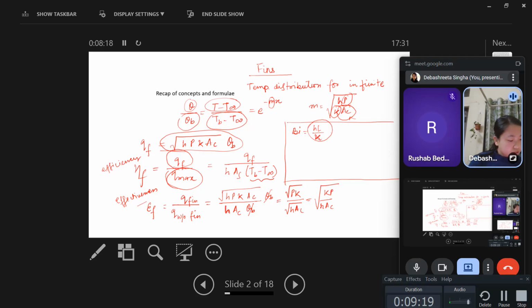Okay, so the temperature distribution can be given as T minus T infinity divided by T naught minus T infinity is equal to exponential of minus t divided by rho V Cp over hA.